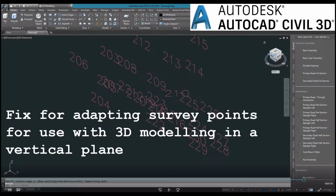Civil 3D seems to automatically default to the horizontal plane for the workspace when you go into it, which is fine if you're using data for a 2D drawing, but not so useful for the 3D modelling. So there's a few steps that you can take to adapt the point data to go into the vertical plane if you need it to. So let's get started.